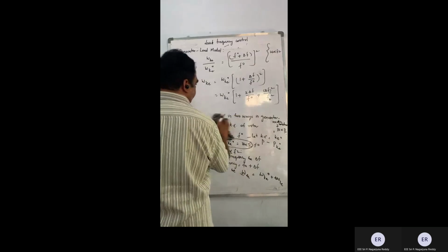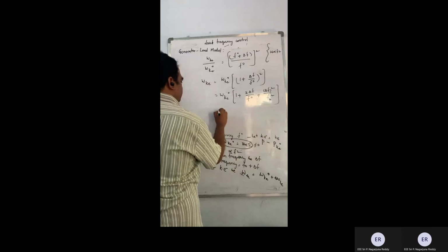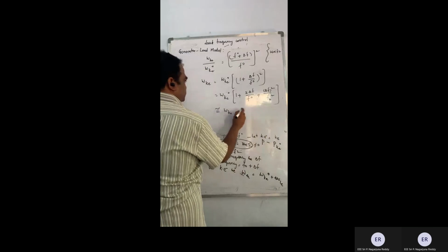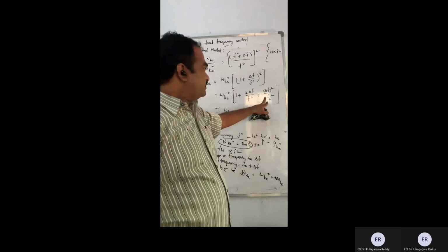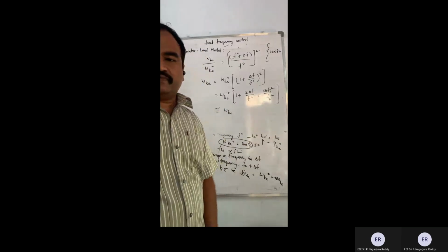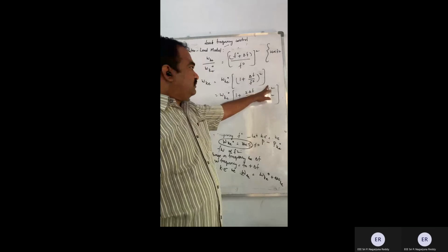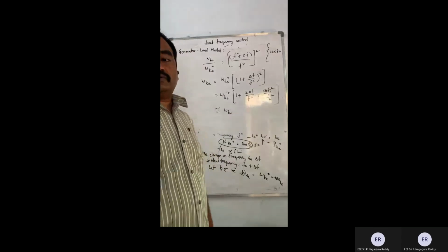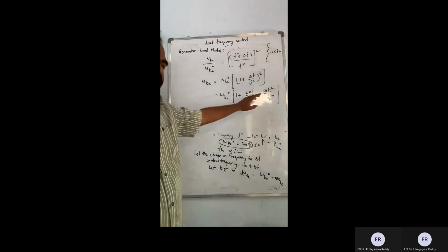Normally this larger term will be neglected. Approximately, when compared to the frequency, which will be somewhere around 50 hertz, and you take a change in frequency somewhere around 1, this term 1 square by 50 square is 1 by 2500. It goes to somewhere around the 5th decimal. So I'm going to neglect this one since it is very, very small.